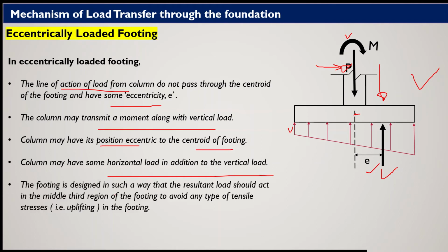Now the footing is designed in such a way, this we have to keep in mind, that when we are designing the footing, we will design it in such a way that the resultant load should act in the middle third region of the footing to avoid any type of tensile stresses, or you can say uplifting of the footing.